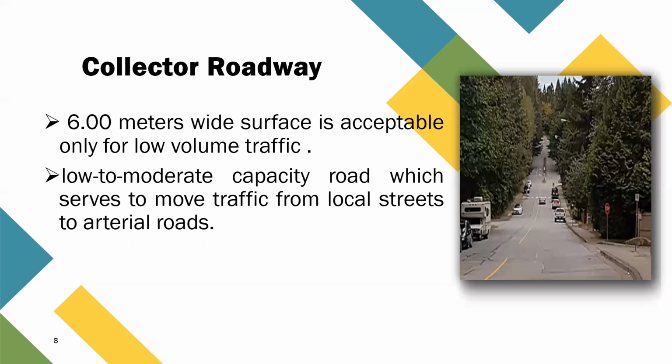Next is collector roadway. For the collector roadway, a 6 meters wide surface is acceptable only for low volume traffic. The collector roadway is also a low to moderate capacity road which serves to move traffic from local streets to arterial roads. So basically, this typical highway is designed to collect or accept vehicles coming from arterial roads and provide access to residential properties and less mobility than arterials at lower speeds and for shorter distances.